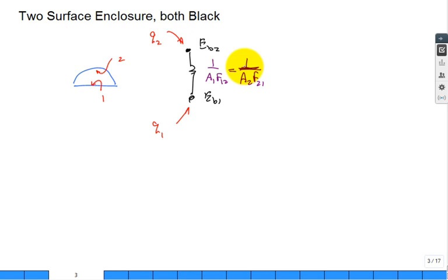All right. Somebody says, maybe I'm given this temperature T1, so I can calculate E_b1. Or maybe I don't know the temperature T2, but if I could calculate E_b2, then I could use it to calculate T2. There's the relationship. So you just have to set up a network like that and be able to solve it for different problems.